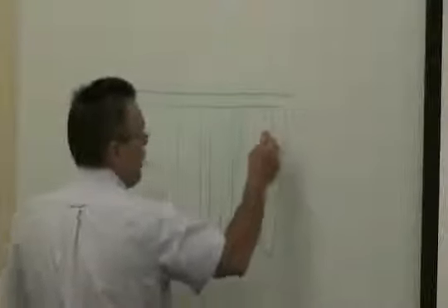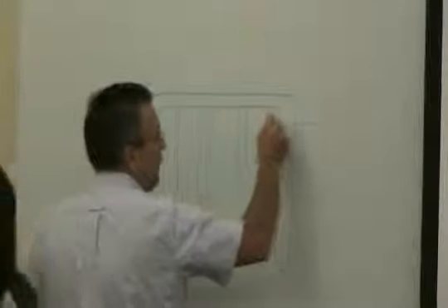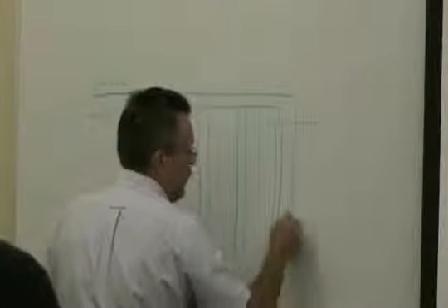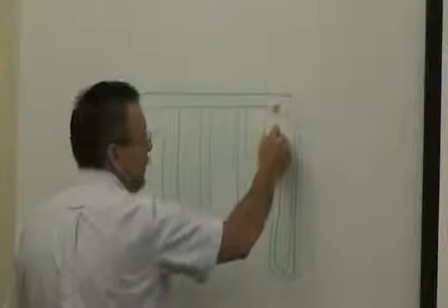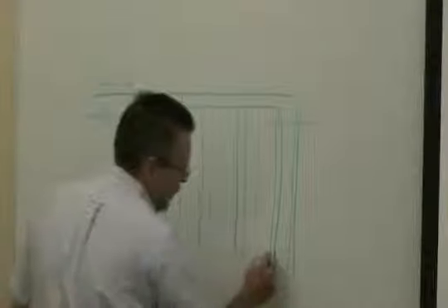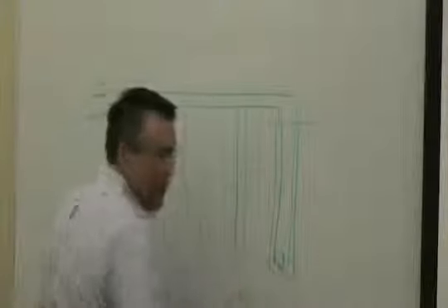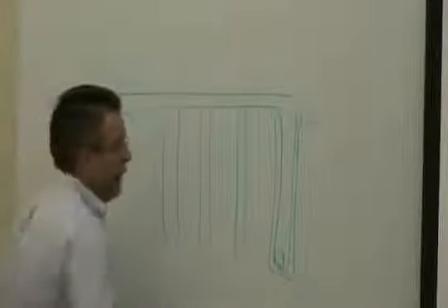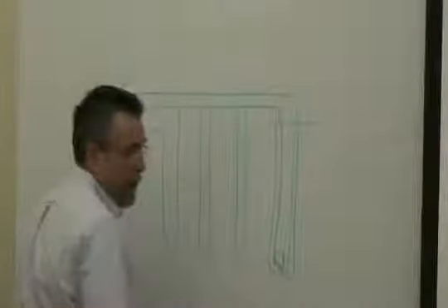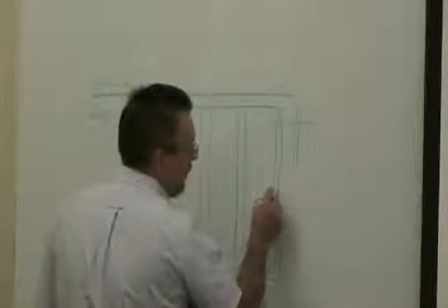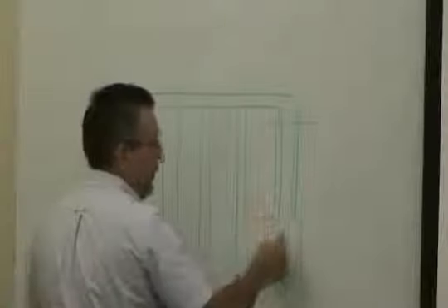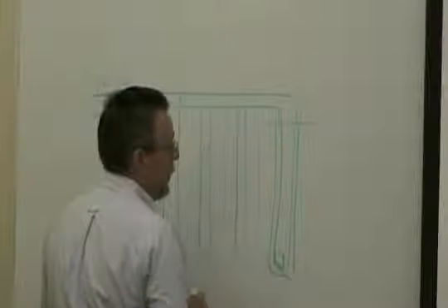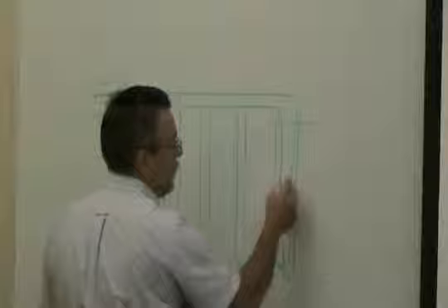Well, is that plus or not? Plus is hitting water. So this is your well. They drill a 6-inch well, and this is a packaged roll of pipe with a typical, very close coupled U-bend connector on the bottom of it. They push your pipe down there with grout, and the grout is very important because it is your heat exchanger back to the ground. There's a special type of grout they use, bentonite or some other type of driller's mud, that acts as the heat exchanger.